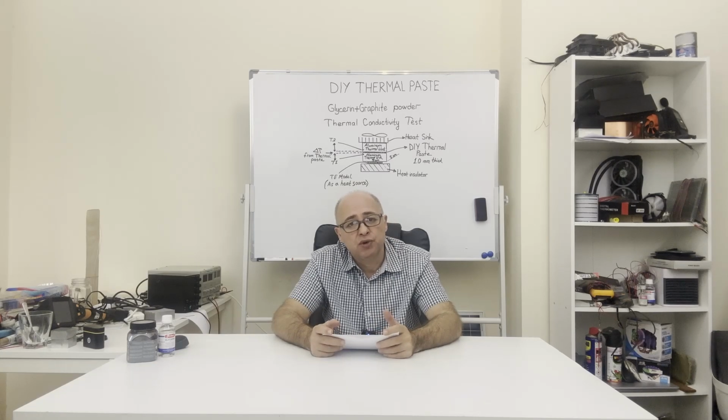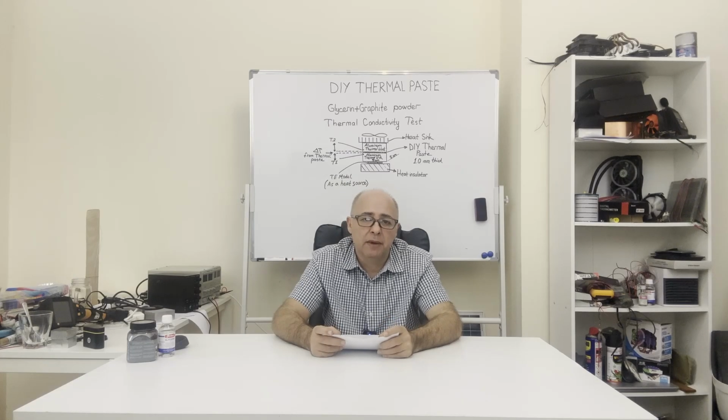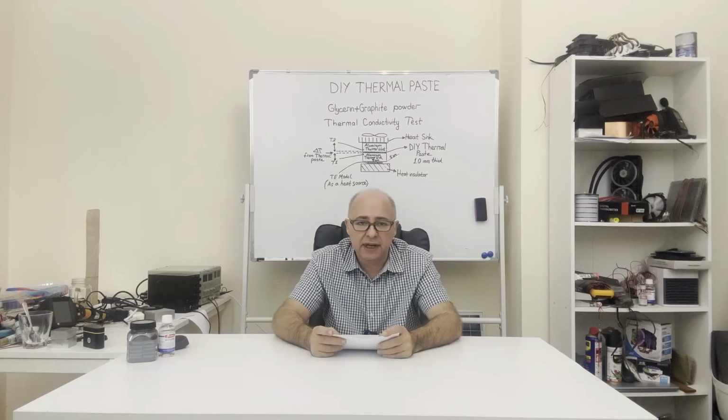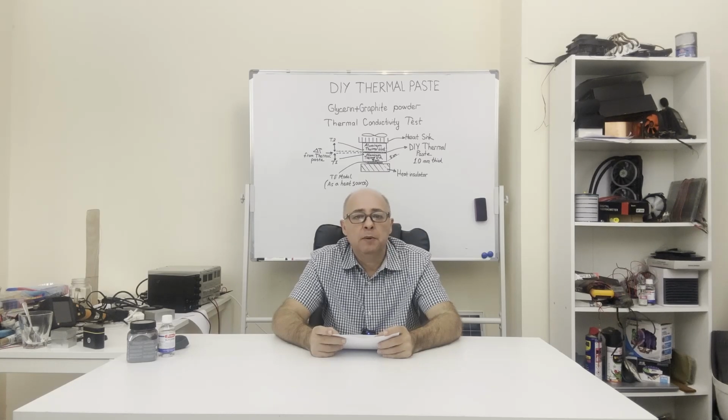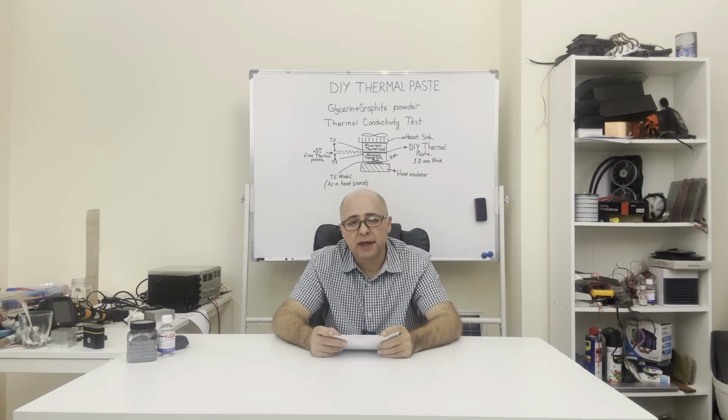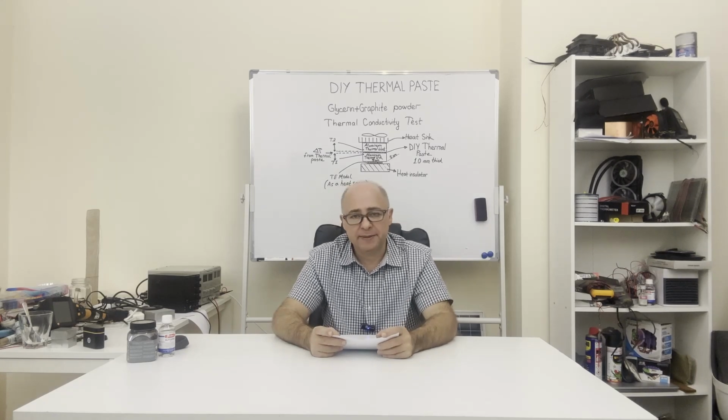Another important issue is that the thermal paste does not leak over time. For this, the sample we produced will be compressed between two surfaces in an upright position and kept for 4 days. White papers will be placed under them to check whether there is any leakage at the end of the experiment. Now let's start our experiment.